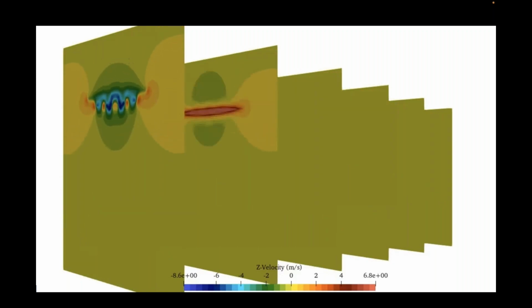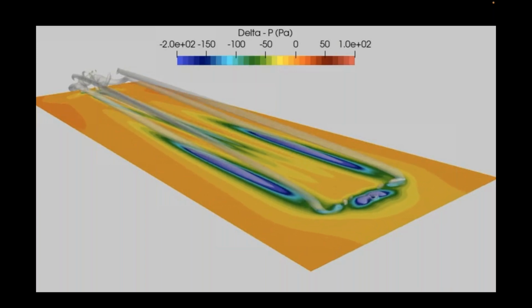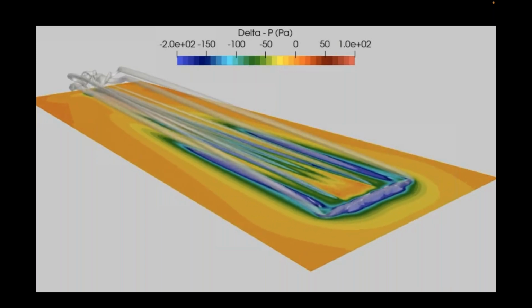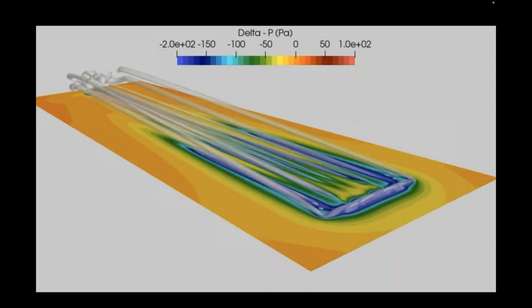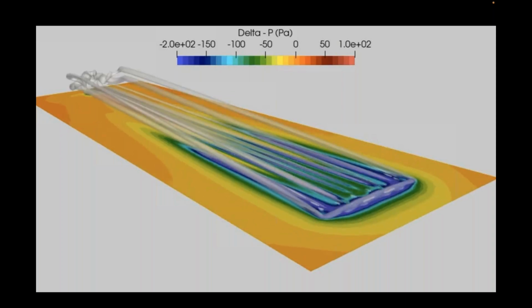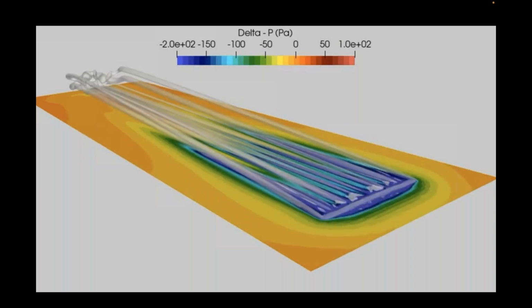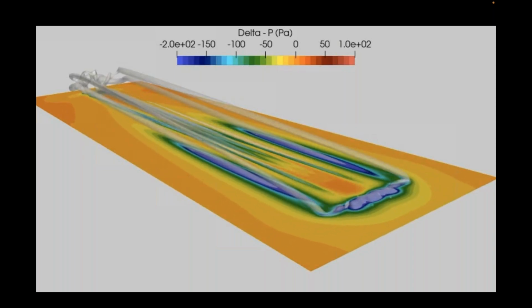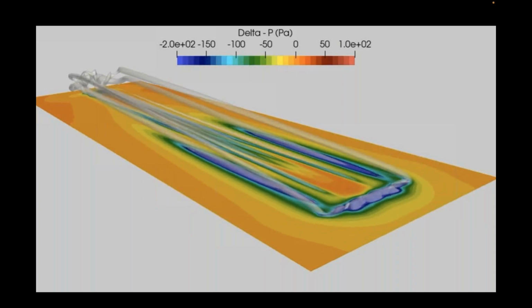The advantage of this approach, as you can see in the next video, is that we're not limited anymore to velocity variables. We can also obtain state variables like pressure, which is very important in the evaluation of structural impacts. So, for example, here we have an under pressure of 200 pascals, that we can then use to dictate whether or not this wake vortex may pose a risk to the structures as well as aircraft.